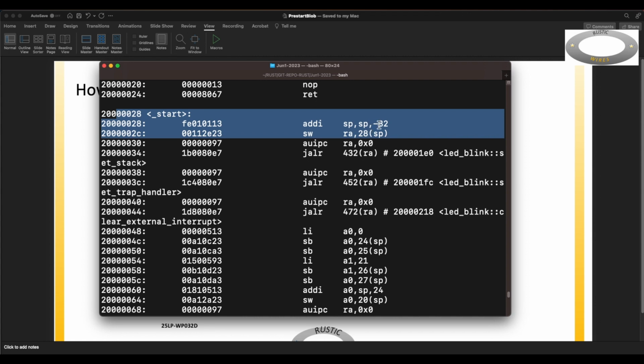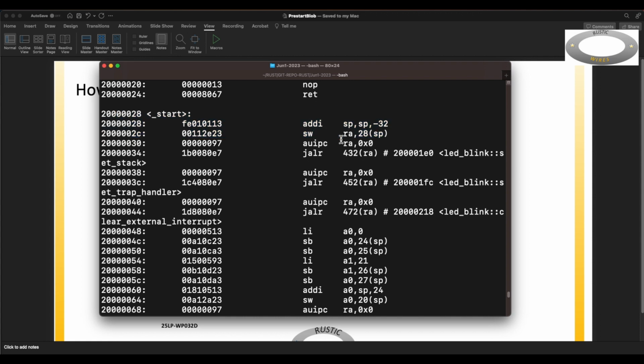I'm not yet thorough on the binary interface for Rust on RISC-V. However, I see from the code that right at the start, embedded Rust expects that the stack pointer has already been set, so it just decrements it by X bytes based on the local variables in start, and starts using it. So the crash happens because of this.